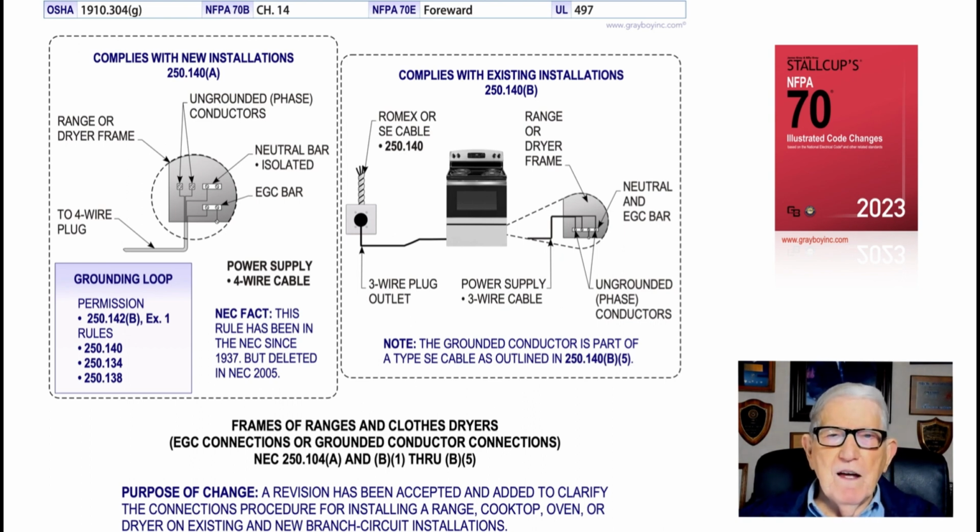Now to the right, you have a parallel hookup, and you can't take 3 conductors in parallel and divide by 3 to size the equipment grounding conductor.